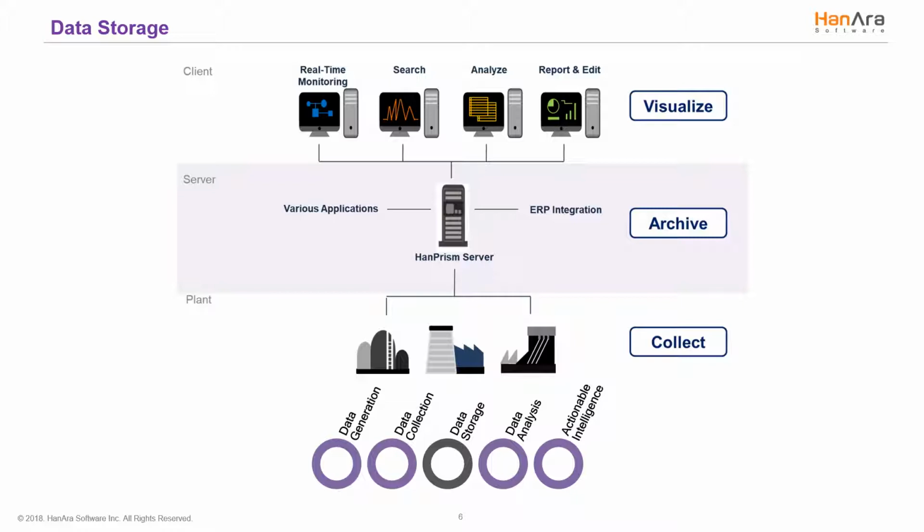So with good data quality, you want to store the data. Real-time data is of course important, but having access to historical data is also extremely important. They say those who don't know history are doomed to repeat it, and it's the same in the process industry. But all data storage is not the same, and data storage should be optimized to meet your needs. Data storage is becoming less and less expensive, but that still doesn't mean that I should store every last piece of data collected. For us, we use a deadband method, meaning we store value changes, not all values. If for an entire day the temperature is at 40 degrees Celsius with no change, I don't need to store 40 degrees Celsius at every minute.